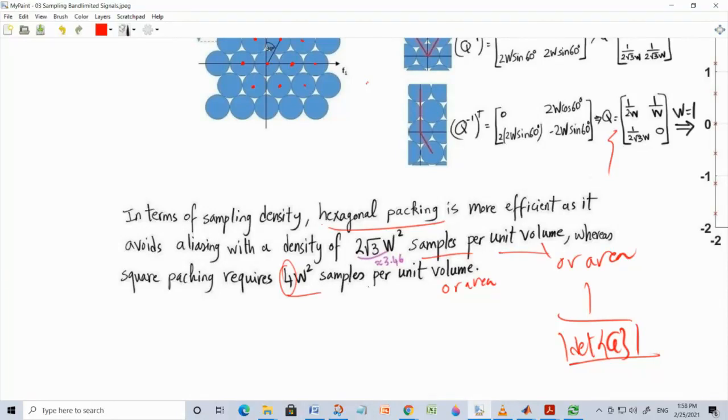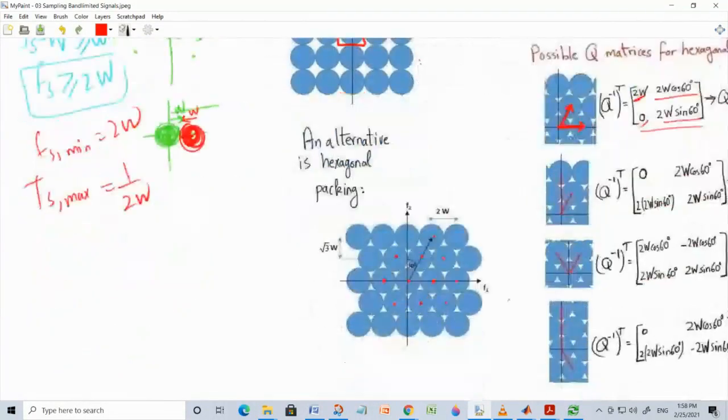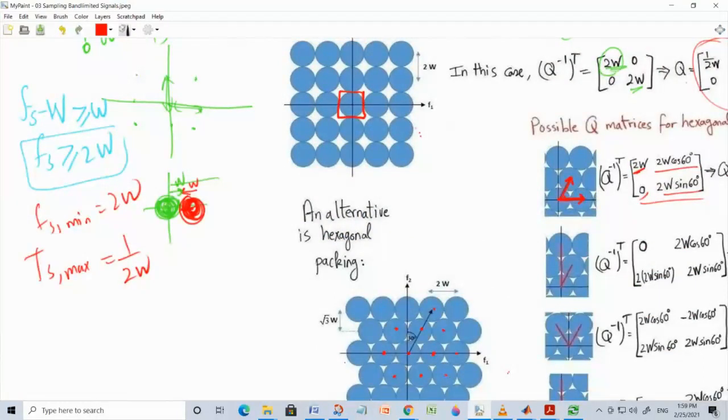In multiple dimensions, you have freedom. How to avoid aliasing in multiple dimensions is not like in 1 dimension. In 1 dimension, you are stuck along the line, so to avoid it you just need this replica to be far from that one. In multiple dimensions, you don't want overlap, that's fine, but you can do so in a number of ways. And so the story becomes more interesting.